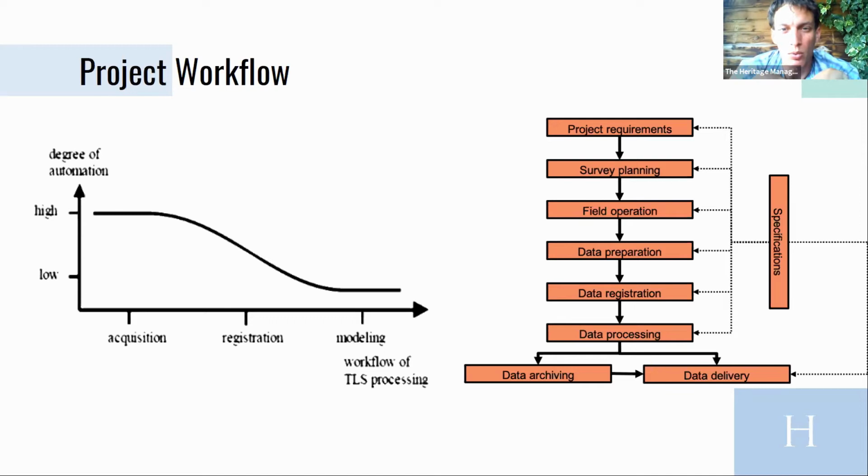The big thing about laser scanning: you are aware that if you use laser scanning, you're able to acquire a lot of points. This is a very big advantage, but also a very big disadvantage. For example, if you have a site and you have the option to use a total station or a laser scanner, it is not per definition always a good idea to use a laser scanner. With a total station, if you have a very simple object, for example a room or just a rectangular area that you want to measure, you set up your total station, you measure 1, 2, 3, 4 points, and you're ready to go, after, of course, setting your backsight or using your resection.